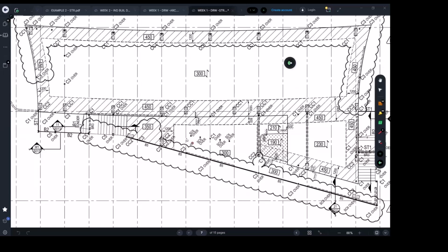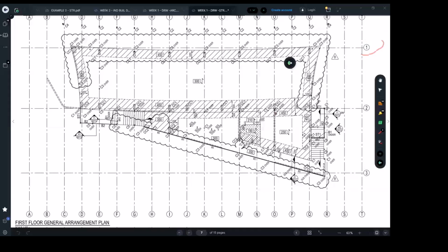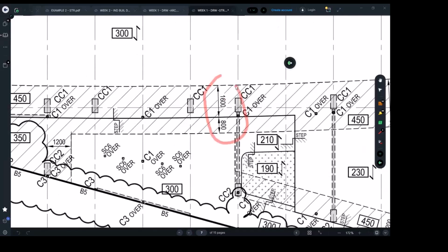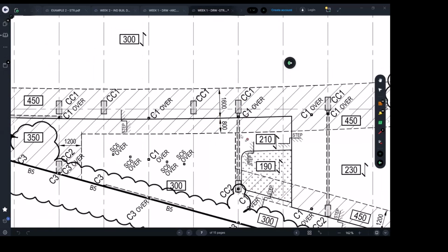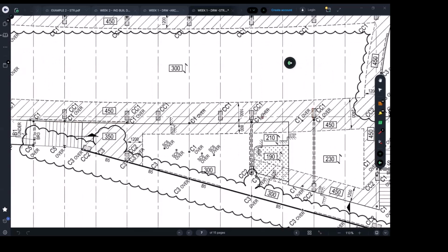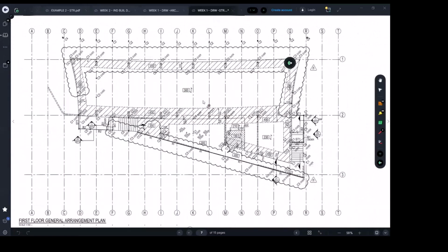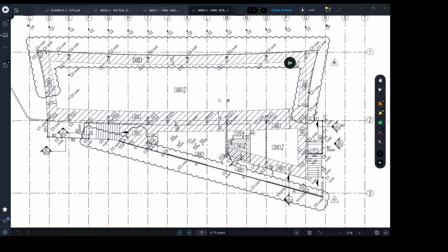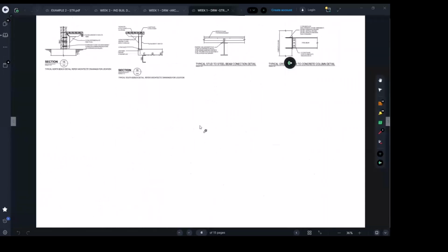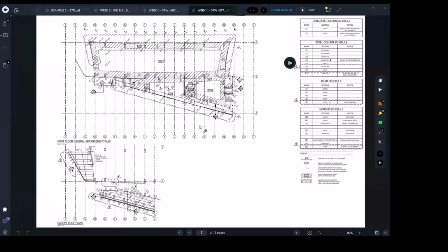So yes, these drawings need time from the engineers to look at. They need to have 4 or 5 hours or maybe 1 day or so to read and start writing down what we have. We have a band beam along grid 1. We have another band beam along grid 2. The band beam is this much of width, which is 2.4 meters, 2,400. So yes, you need to start understanding how the system works. The band beam is supported on those columns, which are below. Same thing here. That was the answer for my first question. In question number 2, the second one, which sheets you're going to use? Simply the answer is you just need to see which drawings are talking or helping you to construct level 1 slab.